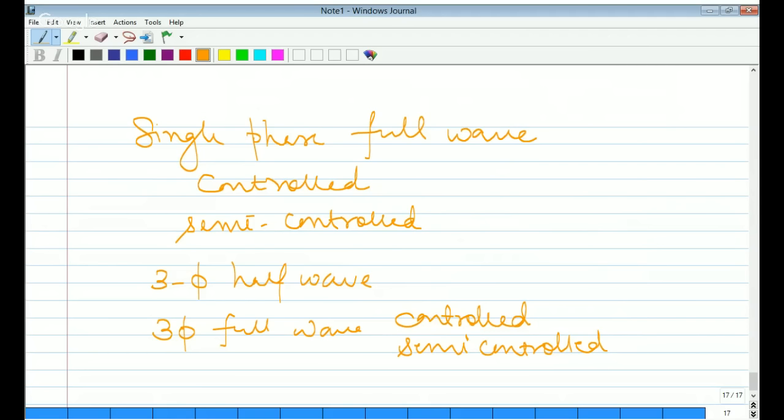Full load efficiency and power factor of a 16 horsepower 440 volt three phase induction motor are 85% and 0.8 lagging respectively. The short circuit line current is 45 ampere at 220 volt. Find the ratio of starting to the full load current if the motor is provided with a star delta starter.